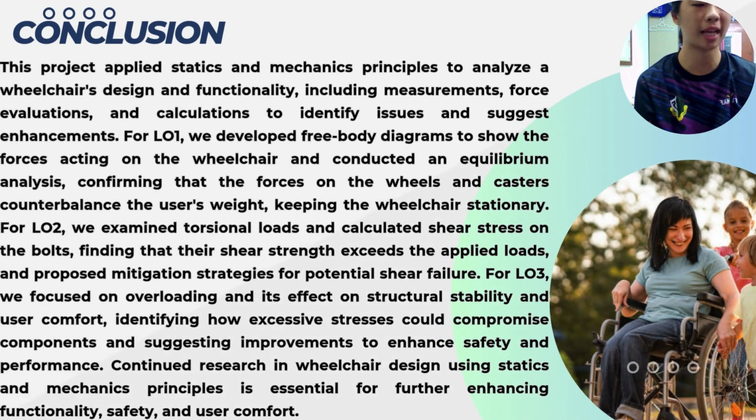In this project, we apply statics and mechanics principles to analyze a wheelchair's design and functionality. For LO1, we created free body diagrams and conducted an equilibrium analysis, confirming that the forces on the wheels and casters balance the user's weight, keeping the wheelchair stationary. For LO2, we evaluate torsional loads and shear stress on the bolts, finding their shear strength as seats apply loads, while proposing mitigation strategies for potential shear failure.